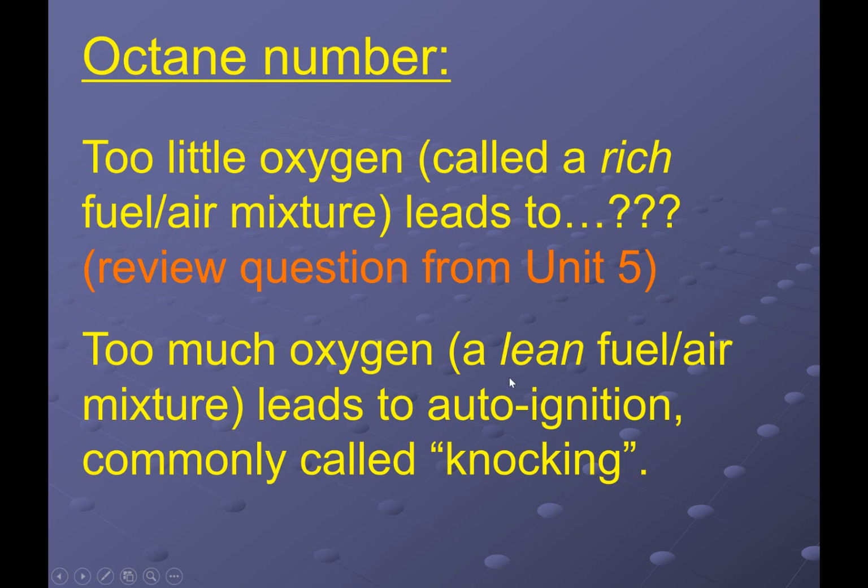In that case, we call it a lean fuel-air mixture, because in this case we don't have enough fuel, we have way too much air, and in this case it tends to produce a lot of this auto-ignition, a lot of this knocking.